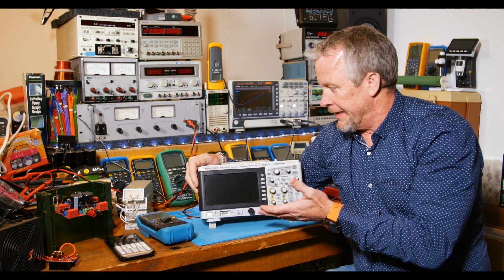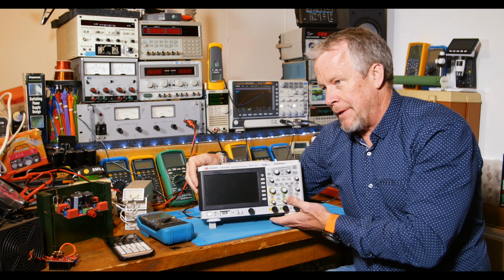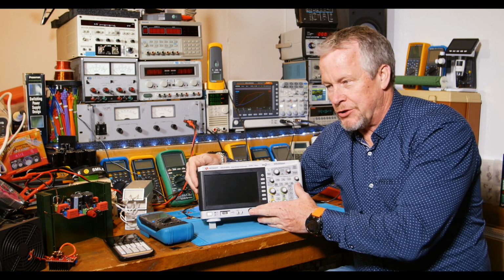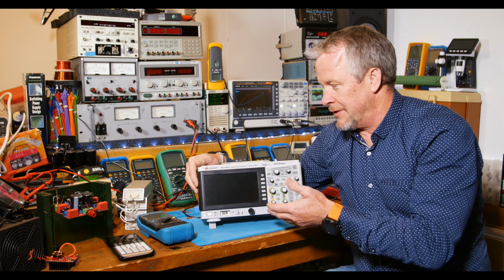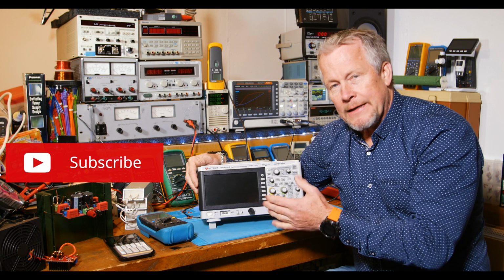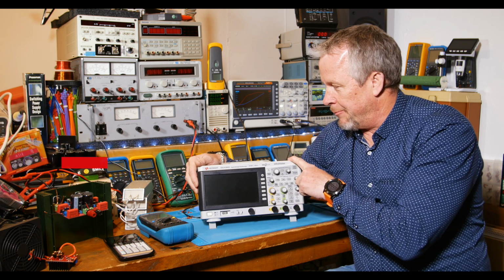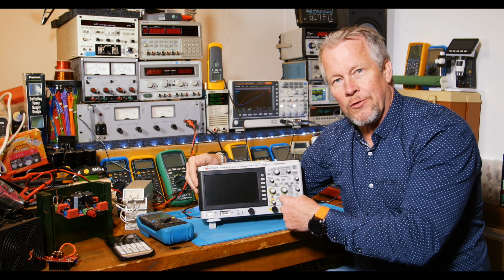So sure, you can get a generator for less than that difference. Maybe even an arbitrary wave generator, which this is not. This is a function generator, meaning you can't create your own waveforms. It gives you your typical triangle, square, and sine, I believe. And it sweeps. So the advantage of getting the generator built into the scope is the fact that it does sweep, and the scope can control that.